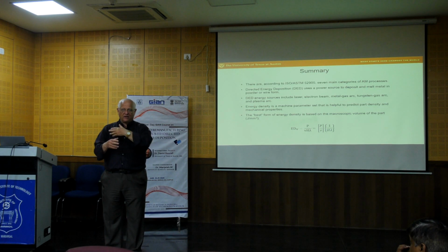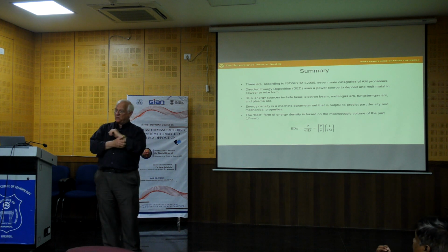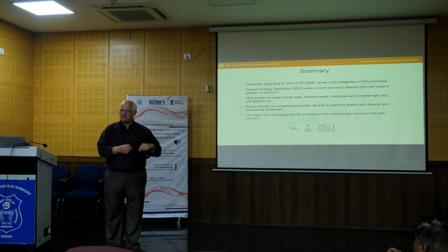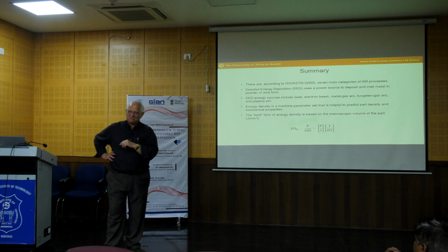And so basically they could lay the carbon black down into nylon, say, very quickly, and then they could just plaster the whole surface, and you can build parts very quickly that way because we don't have to scan a laser beam over the entire surface. That's half of HP's process.